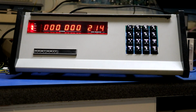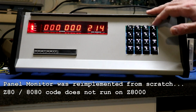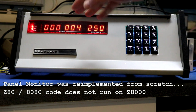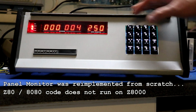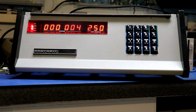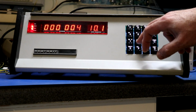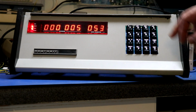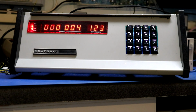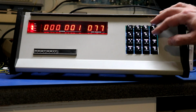So it comes up and the panel monitor loads just like any ordinary H8 computer. We can go forward through memory. We're currently looking at address 000004, and it has a value of 250 octal. Now we could change that if we wanted to, so I'll hit Alter. 1, 2, 3 automatically goes to the next address. So if I go out of alter mode, go back, there's 123. I'm just blowing away random addresses in memory while the computer's running.